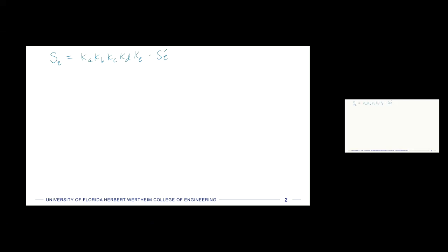I'm just going to cover this briefly. If you need to apply these for a homework problem, or according to some system you're trying to analyze, it's really helpful to just look things up on charts, but I wanted to give you at least the range of how much they affect things. So the first one is the surface factor. And we said last time that all of these factors are below 1, so they reduce the endurance limit.